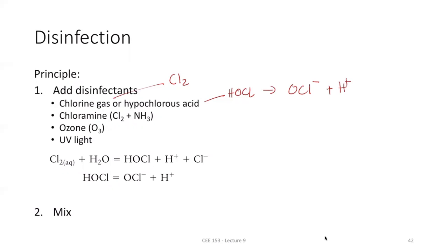That's why people use chloramine. Chloramine is basically chlorine gas with ammonia, and when they react together, it forms chloramine products. We actually call this combined chlorine, because it uses chlorine. The reason this is used is because it is more persistent, which is useful for the distribution system. When chlorine combines with NH3, it becomes monochloramine, NH2Cl, plus HCl.